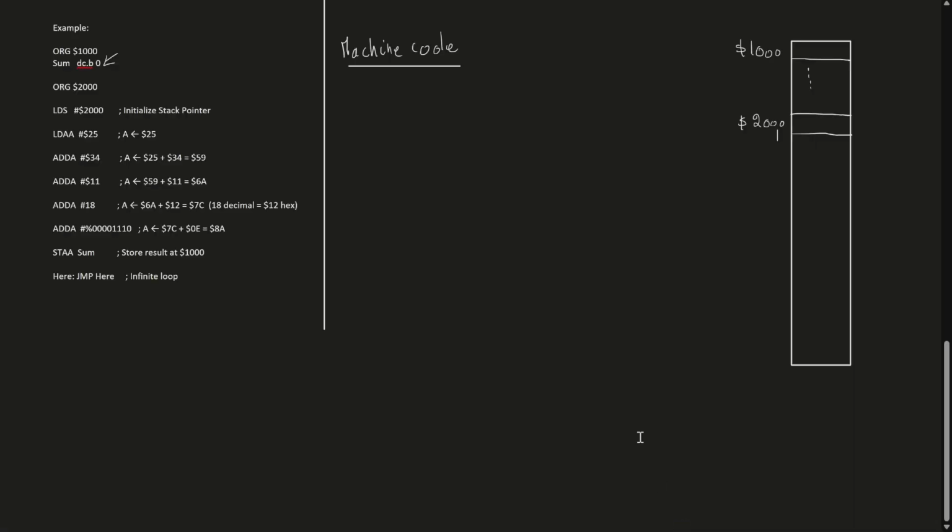So let's go back here. The machine code for this specific instruction, as we saw, is CF. And all of these, when I put the $, are hex numbers, hexadecimal. And then the JJKK are going to be obtained from here. 20 is for JJ and 00 for KK. So the machine code for this instruction will be CF2000.